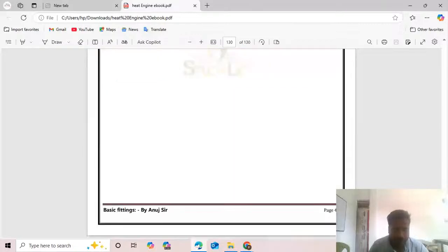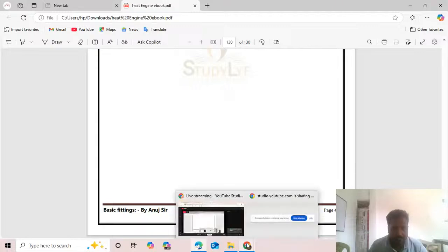So in welding, we have already discussed gas welding, friction welding, and arc welding. You can say which one is the consumable electrode and which is the non-consumable electrode. For non-consumable electrode, you will see that tungsten TIG welding uses a non-consumable electrode.